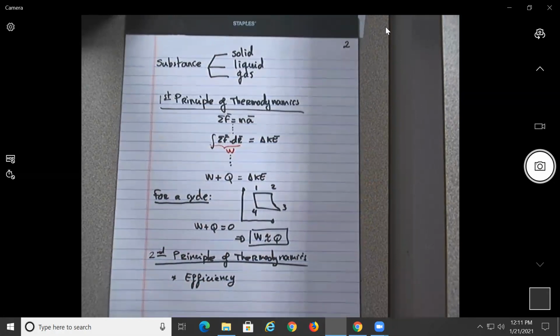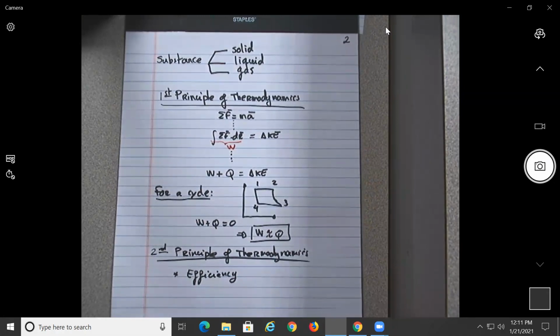So the two deficiencies are one that is the efficiency, and this one, I'm going to explain it now. It's very easy to understand, quick, but it's very important to understand. I'm going to repeat it probably 100 times in this class. Why can a system not be efficient? A thermodynamic system is always going to operate between two temperature reservoirs, between two temperatures. So for example, if you have your car, your engine running, it is at a certain temperature, but it's running relative to the ambient temperature, correct?